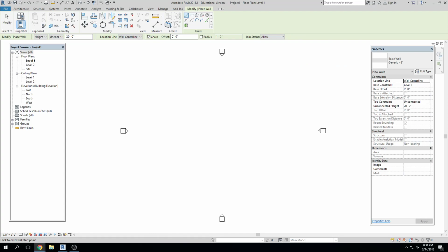And the idea behind storefront is that you have this opening, like in the brick, right? And the opening has structure built in above it, a header, that supports the load that's coming down on it here. And so the opening is essentially supported by the header, and so when they put the storefront in, it's not structural, right? The storefront just goes in, and it's a glazing system that you can see through, but it's not by any means interacting with the structure at all, okay? So that's the idea of storefront.